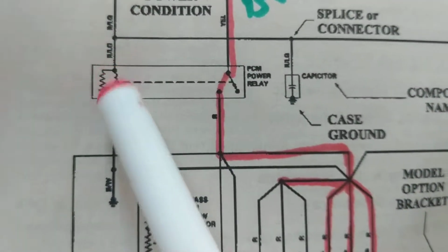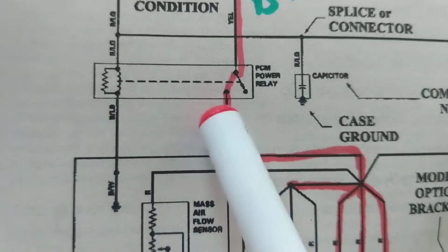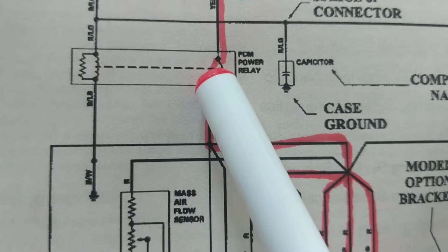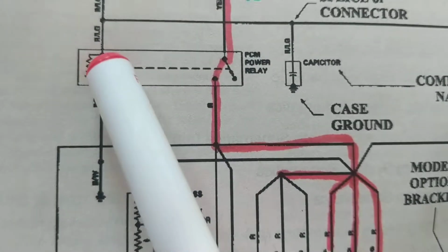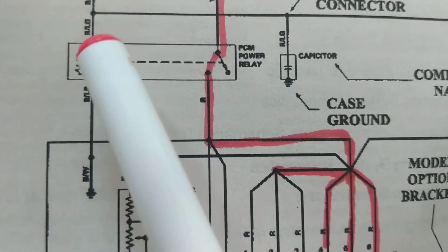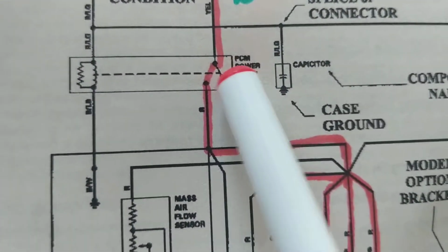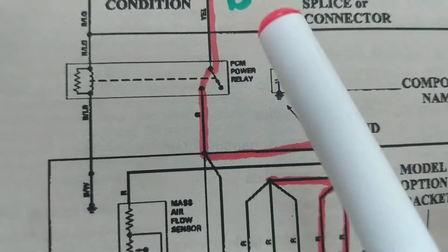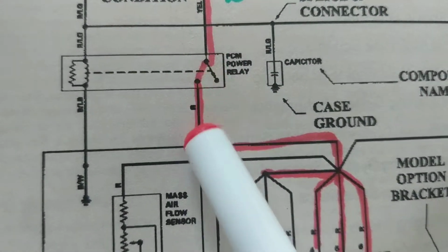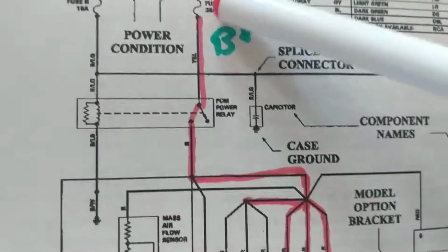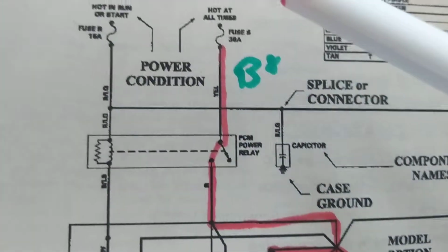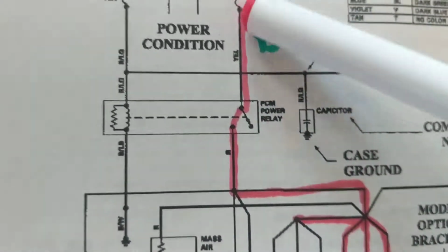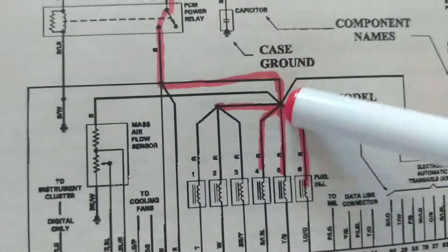Current flows here. As I've stated in other videos, how it happens, this creates a magnetic field around this. The switch is now flipped. The dotted line means that this is controlled by this. When this current flows here, this switch will flip over here. So once this flips, we know that it closes the path for another circuit. So we look for another path of circuit. As you see over here, B+, and I dotted it in red, the B+ will follow in this.